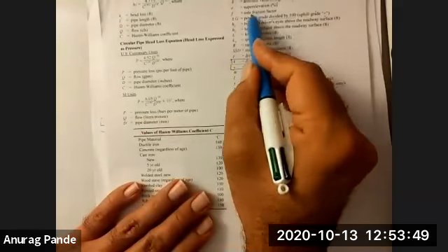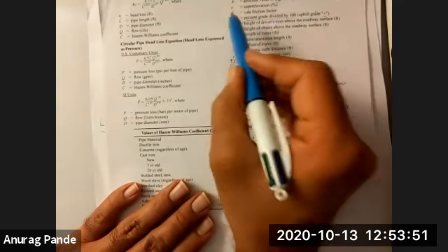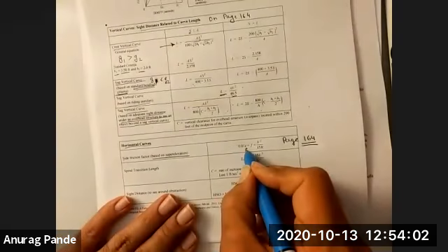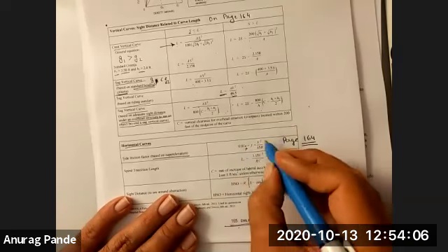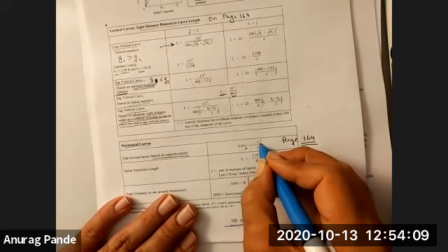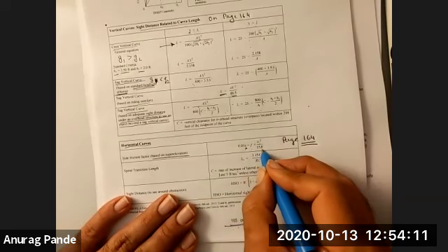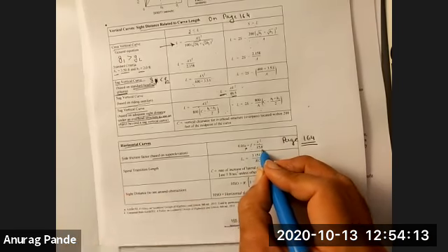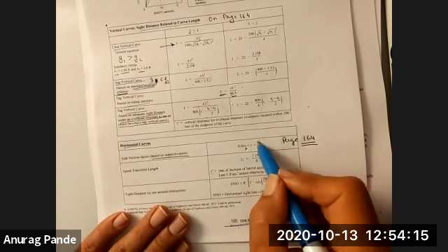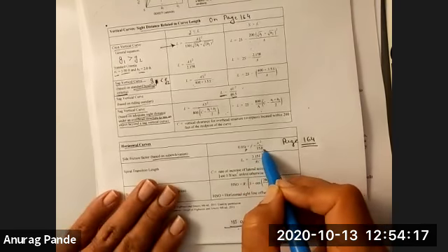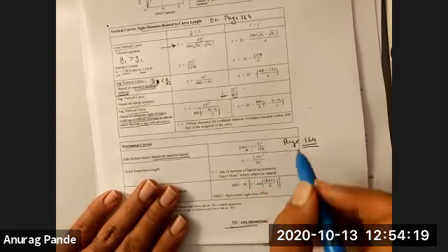Small f is the side friction factor. Small e is the super elevation as a percentage. Again, units are very important. So if I say that super elevation is needed at 8%, then you will put it as 8 here. Okay, and then capital V is the design speed, so you'll enter that in miles per hour, and R is the radius in feet. And again, the units are consistent, so you can plug in V in miles per hour and R in feet, and you'll be fine.